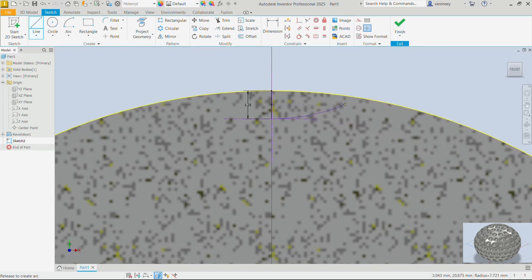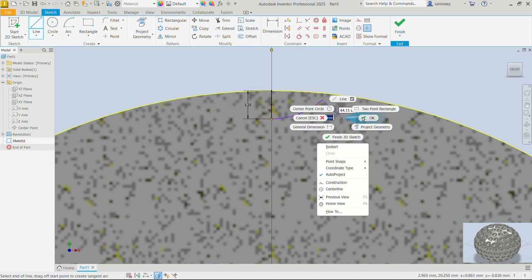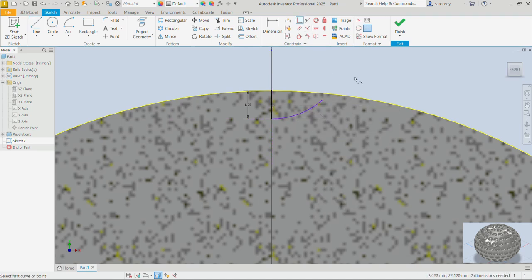If you connect, you get a weird profile. So let me drop this here. You can right click OK and rather make coincident this point and this arc. There we have it. Now we can dimension the distance between this point here and this point as 2.25. That would fully constrain the sketch. We are ready to revolve.